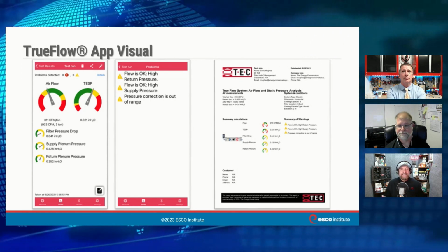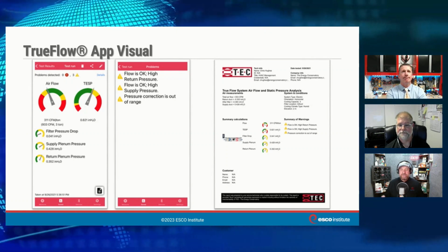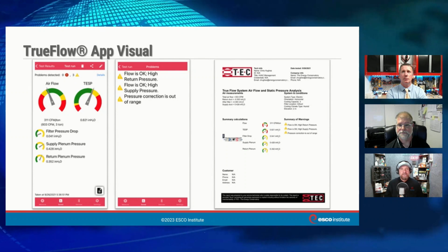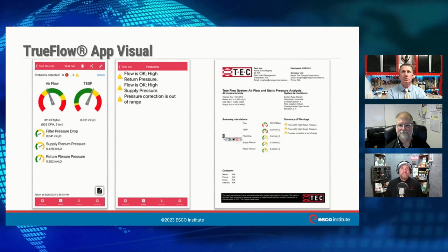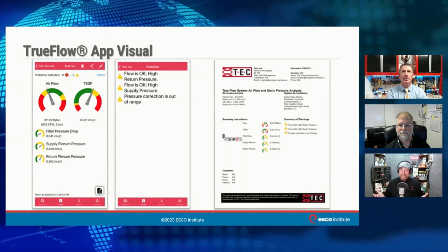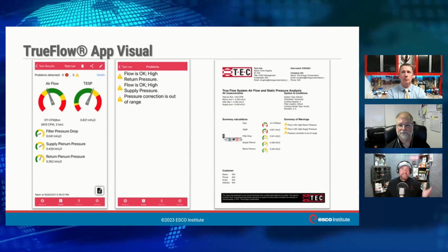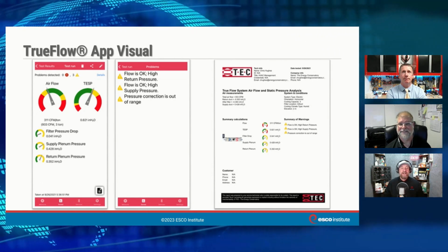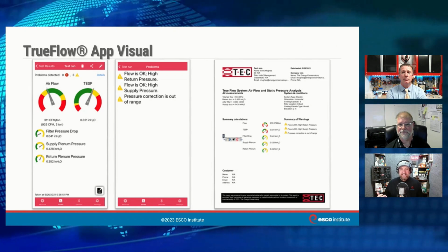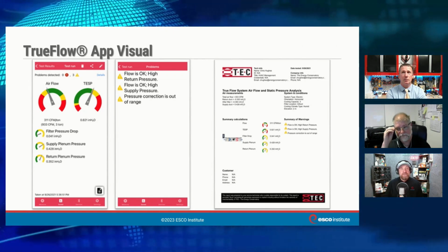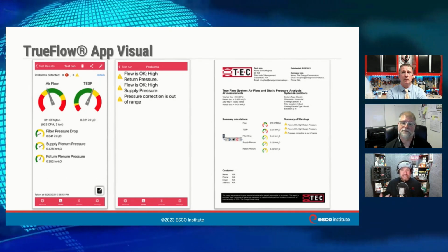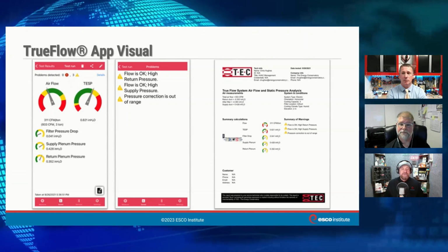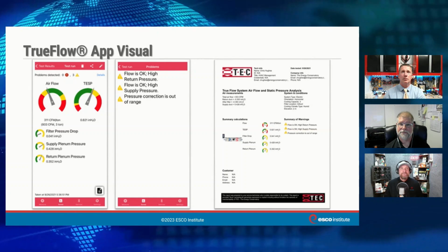And it's in the numbers, because we can have a customer that has 5 or 6 times they've been to the house and the return air is too small. And I was like, well, it's always been that way. Well, now you have something else backing you up saying, hey, nope, validation. The numbers also say, and the little red and green dial also says, hey, this is where we have a problem. So it does simplify that. It makes that conversation with the customer easier and faster. It makes your job a whole lot easier and faster, and it makes that system work better. And once you start doing this, everybody wins.